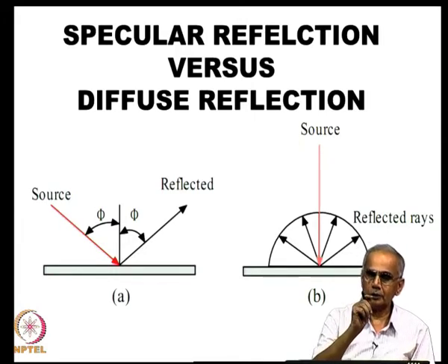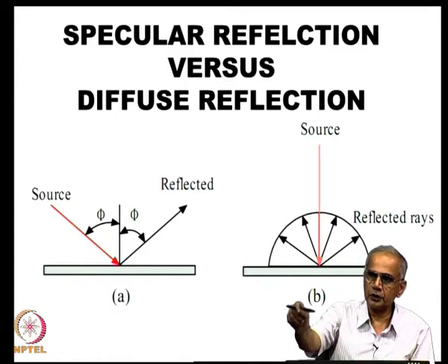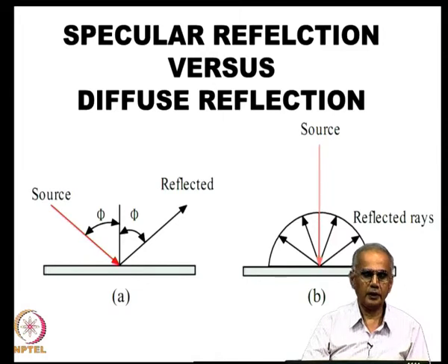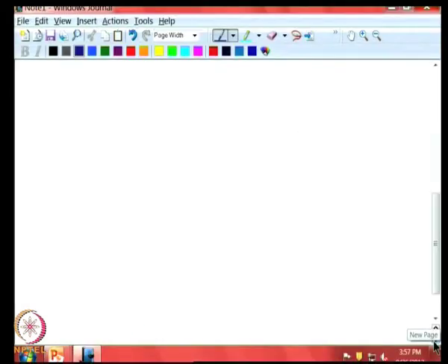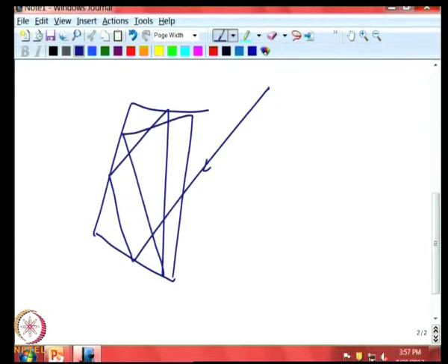You have to look at each photon and trace its path through the enclosure as it is reflected in a specular fashion in a given situation. So, let me give an example of that. Suppose your enclosure is like this and radiation came like this, you have to follow the radiation reflected like this, like that, like this. So, you have to follow the ray through all these reflections.